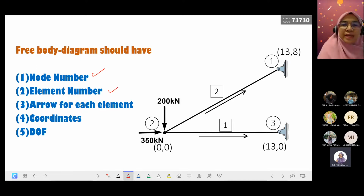We have element 1 and element 2. An arrow for each element, also have. If you don't have, you have to put all this. Then the coordinate, we have to put the coordinate. So choose one joint as origin. This time I choose node 2 as origin. So based on origin, we label the remaining joints. The coordinates for the remaining joints, we get 1 as 13, 8 and 3 as 13, 0. Okay, this is the coordinate.